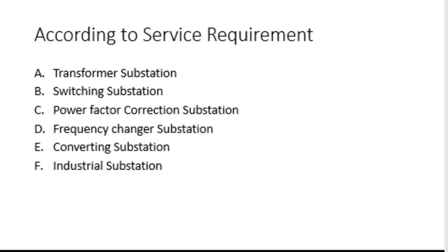Next is the power factor correction substation. Simply, as the name suggests, there will be power factor correctors. For the power factor correction, I have already shared some study material by Oza sir. If you have gone through that study material, you already know that for power factor correction what we need is nothing but capacitor banks, because capacitors are the best means for correction of a power factor.